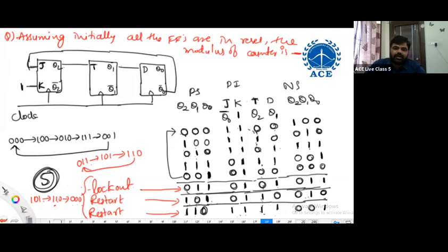It's not like glitches, Rajendra. It's like when the counter is started, depending on where it has stopped, which state. In the off condition, there may be dischargings. The dischargings may be completed on some flip-flops, and some flip-flops may not be discharging. In such cases, there is a possibility of seeing an unused state when the counter is started. All of this can be eliminated with one thing.